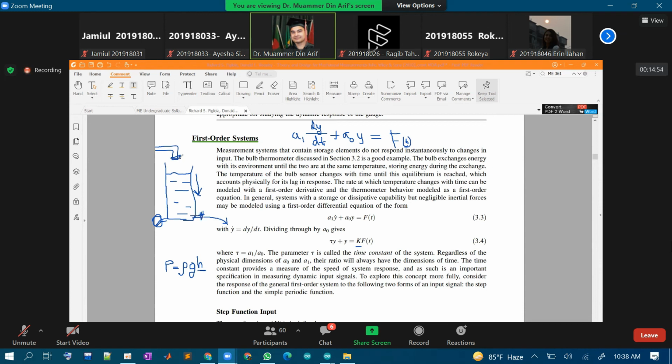Now on top of that, if I start this tap, it will be adding water to the top. Depending on how fast this is going out and how fast this is filling up, the pressure reading will come. Now here is the catch. The higher the level when I start the upper one, the bigger this difference will be. Why? Because how fast water comes out here depends on the level, the pressure. The more water column, the faster water comes out. As it comes down, the pressure becomes less, so